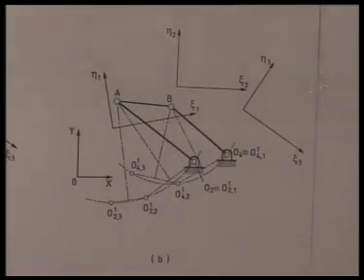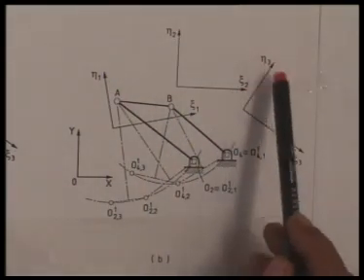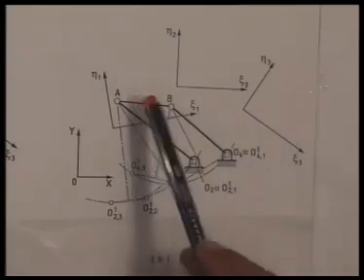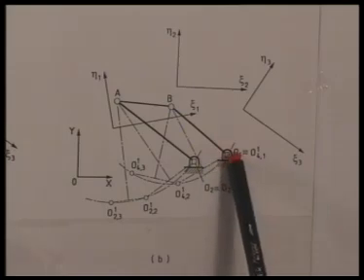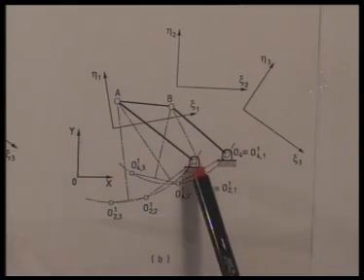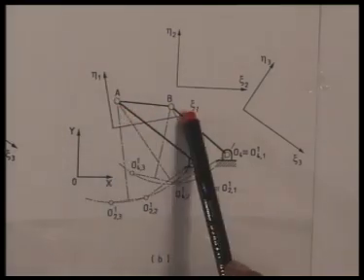As the principle of kinematic inversion forms the basis of this procedure for dimensional synthesis, let me repeat it once more, the solution shown in this figure. What we have done, we are using a tracing paper, eta 1, zeta 1, eta 2, zeta 2, eta 3, zeta 3. They specify the 3 desired positions of the coupler. O2 and O4 have been chosen according to the convention. Our task is to determine the location of the moving hinges A and B. Say we want to decide it in the first position of the coupler.